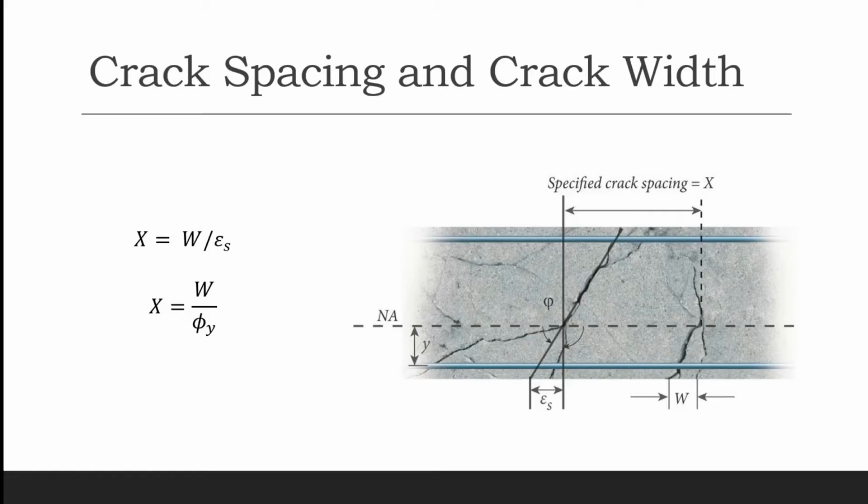And if we assume a certain crack width, then we can determine how far apart such cracks will be, again based on the strain that we have determined from the moment curvature curve. And this strain actually corresponds to a certain moment, including all of the material behavior that we have included in our calculation.